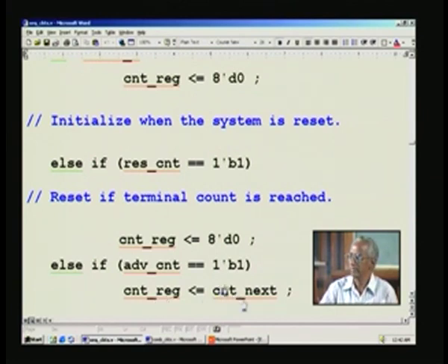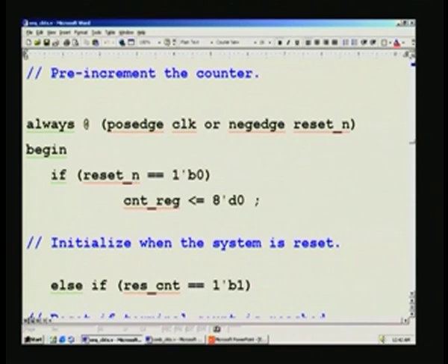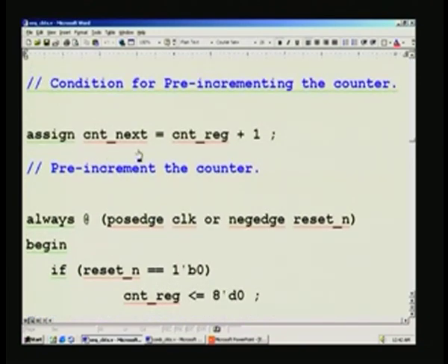You may think, is it not going beyond the time? It will not, because whatever is pre-computed here again depends upon this register only. So it will not keep on incrementing, because it is assigned in an assign statement, which is a combinational thing, right. So it depends upon the counter edge. So this will change only with the arrival of the positive edge of the clock. So you can rest assured that this also will change only subsequent to the arrival of the positive edge of the clock.